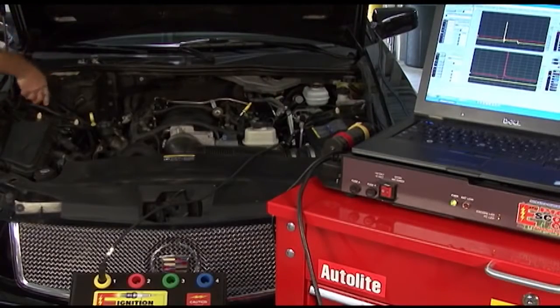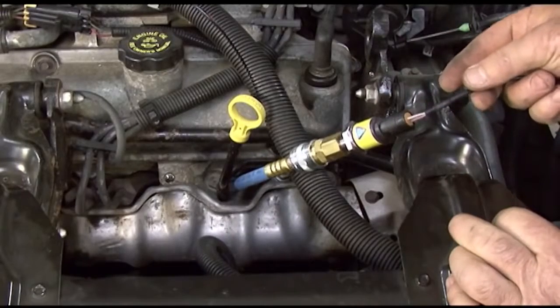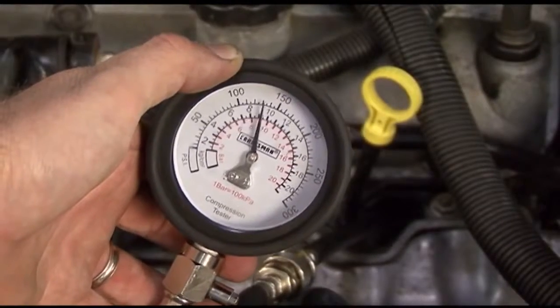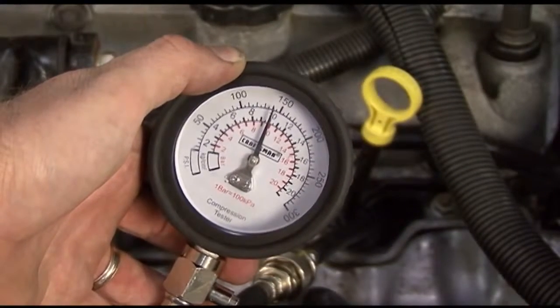There are many potential mechanical causes of misfires. Start by checking engine compression on the offending cylinder. This can be done with a big box analyzer or an oscilloscope and a high amp probe. If these diagnostic tools are not available, start your normal compression testing on just the cylinder that you detected the misfire on. Record the cranking compression reading.